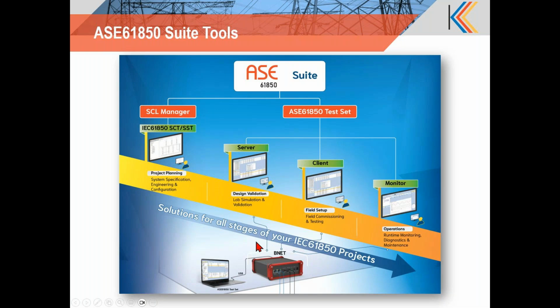The high processing capability of the BNET will allow you to do a lot of advanced troubleshooting on the process bus network. It can identify missing packets or delayed packets in the network. It can find drastic RMS changes and angle changes in the currents and voltages. So it can scan the sampled value packets in the network. A lot of capabilities with respect to the process bus are available in the BNET hardware.